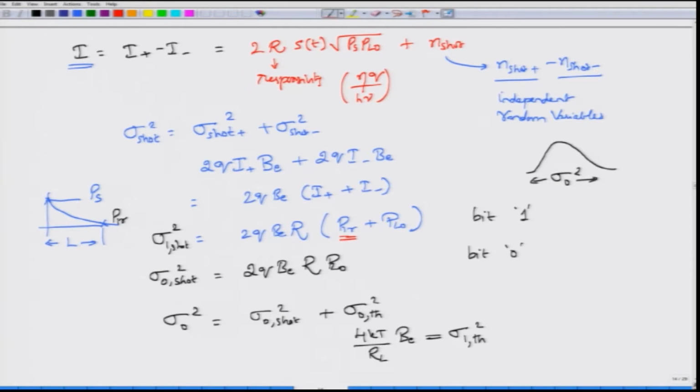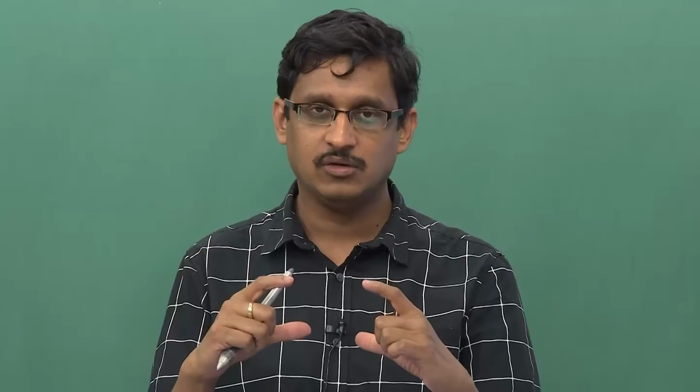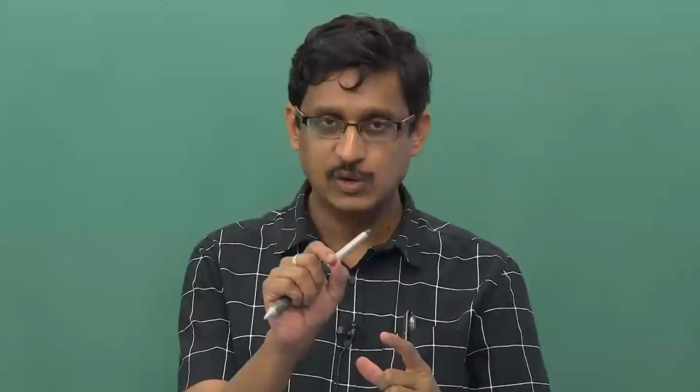However, at lower powers it is not really so. So you actually have a variance which is changing depending on the length of propagation. This variance of sigma 1 square depends on the length of propagation simply because P1R depends on the length of propagation. So setting the threshold will now be very difficult. You can't have a simple coherent receiver circuit and say, okay, go ahead and use it, because then someone also has to tell you the length and you have to do a manual adjustment of the thresholding that separates bit 0 and bit 1.